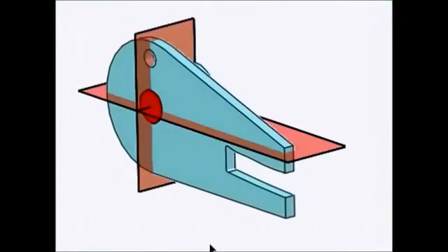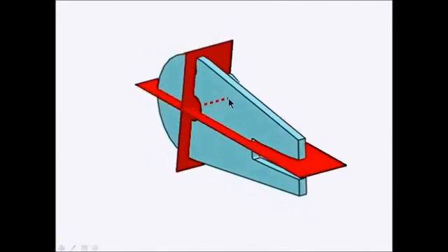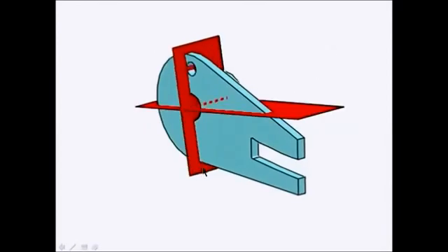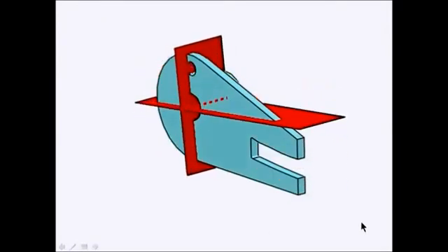As I mentioned, first you would fill datum feature A with the largest inscribed cylinder. This gives you an axis. The axis is the intersection of two mutually perpendicular planes. The question is, how do I now orient these datum planes? Well, the slot was picked as a secondary datum feature. There are two ways that I can use this to orient the planes.